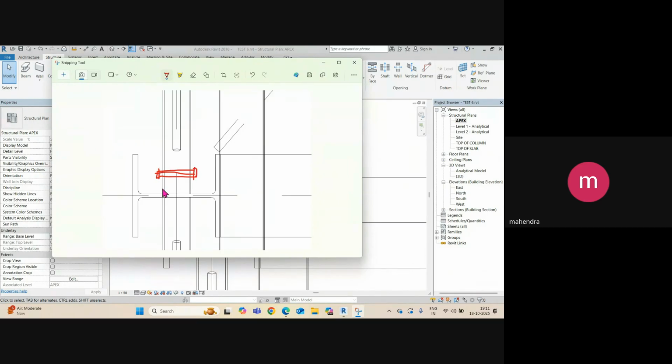The beam is welded to the column in fabrication, and after that they just bolt this member and this member. Then you need to add the gusset plate. So suppose this is my gusset plate in this direction. Okay, like that. In that case you can just change your working point. So instead of here, you give it just here, and then you can add the gusset plate. This gusset plate is welded to this beam, and you can add the detail here.